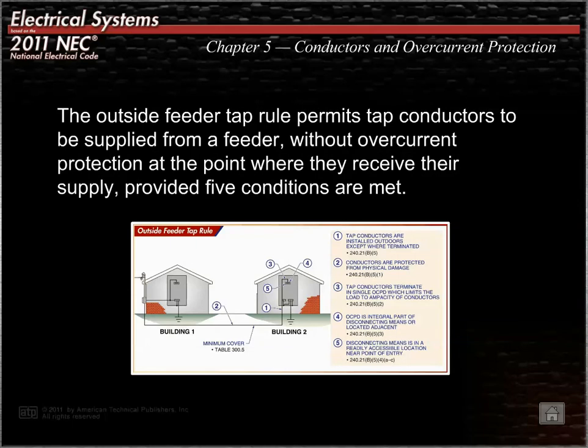Outdoor feeder taps are permitted without overcurrent protection at the tap where the conductors are located outside, except at the point of termination for the conductors.